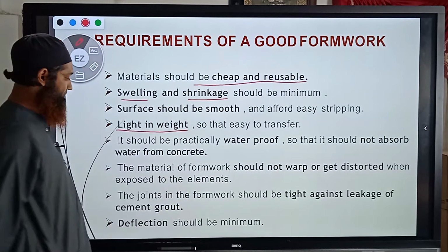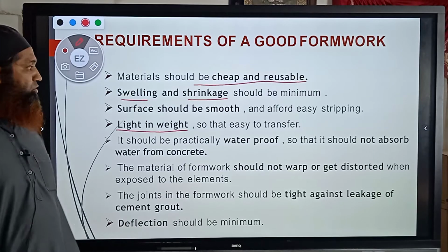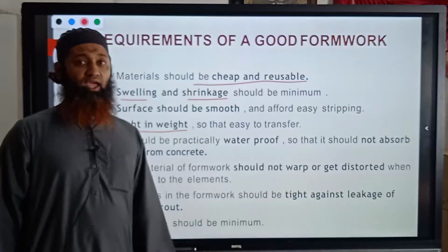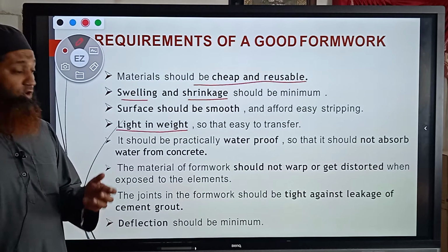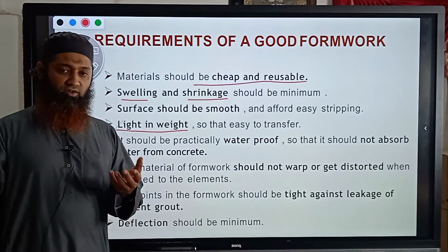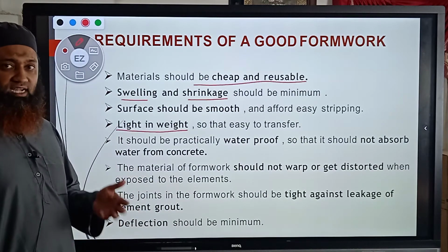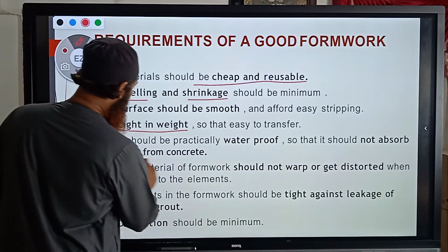It should be light in weight also. It should be practically waterproof so that it should not absorb water from concrete. See this, as I had told you, it should be waterproof. We should try to come up with a formwork which is waterproof also. If it is not waterproof, then the formwork will take the water, and because of that there are chances of swelling also. So it is very essential it should be waterproof also.